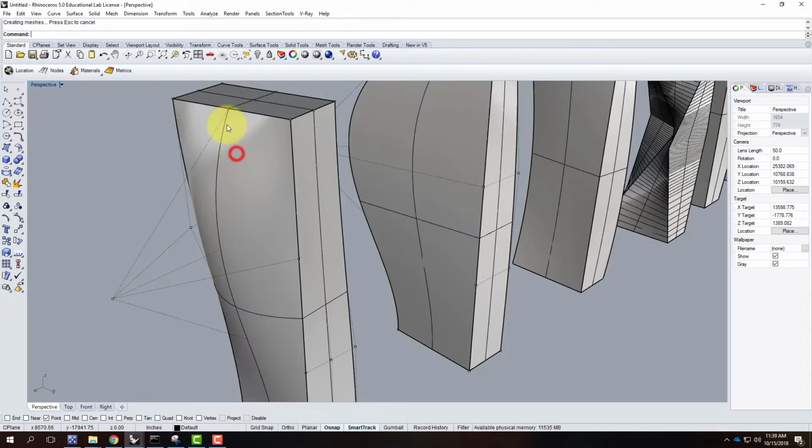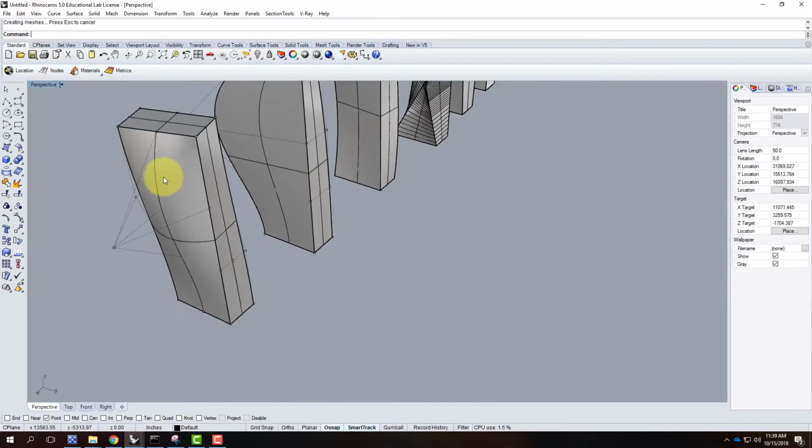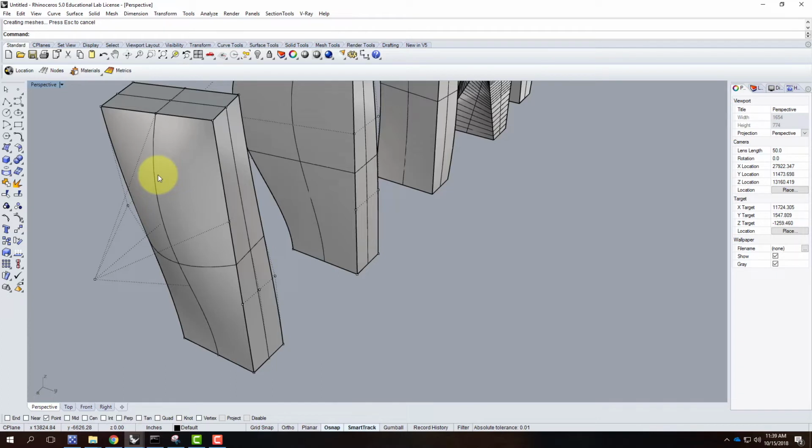So if you can, try to stay away from that kind of curvature, as sexy as it can look. In practice, this is really difficult to build. If you went to a contractor and said, I want to build this building, they would have a really hard time engineering it and figuring out how to build it. Most of the twisting surface buildings that you see out there are not this kind of surface. They're still straight line surfaces, where they appear to twist. It's called a ruled surface, where the straight line twists. That's a very doable construction technique.